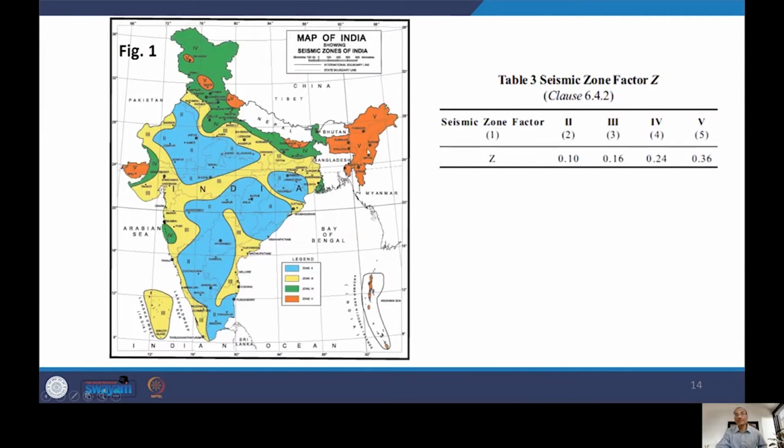Most of you may be aware of the seismic zoning of the country. Here you have the highest zone, seismic zone 5: all of the northeast, the Andaman and Nicobar Islands, and some part of Bihar, that is basically North Bihar. Then parts of Uttarakhand, where Pithoragarh and Almora are, then part of Himachal Pradesh, Mandi, and part of J&K, that is the capital Srinagar.